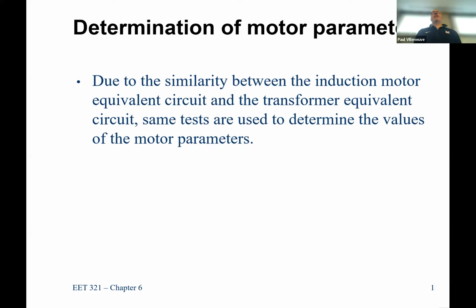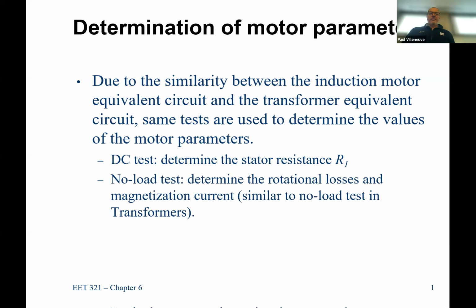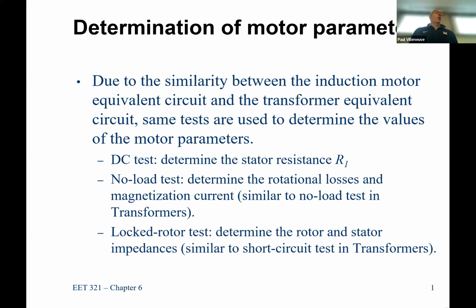Okay, we're going to do an open circuit test and a short circuit test, or we're going to do a no load test and a load loss test. What would be the equivalent for an induction machine? No load test just means run it at very light load, almost none. So you just have the friction and windage losses.